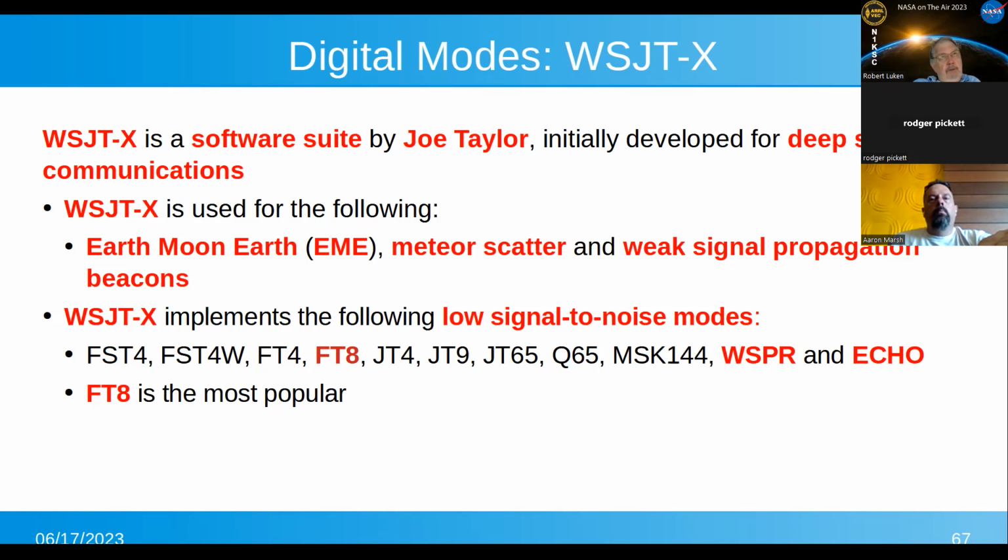It's called FT8 because it uses 8 low frequency audio tones to represent the binary data. So in effect, it sends 3 binary bits for every character that it sends. And it's 50 hertz wide. So it's very narrow bandwidth.